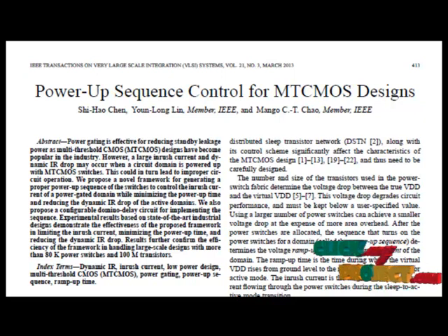Therefore, inputs can only be applied to a pipeline stage once the supply voltage has reached an acceptable threshold. By leveraging the supply voltage operating range of asynchronous circuits, we can avoid these requirements and begin useful computation before the supply voltage has stabilized, reducing the forward latency seen by the first input token.